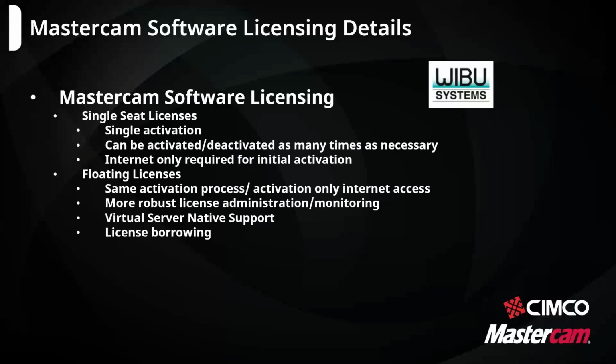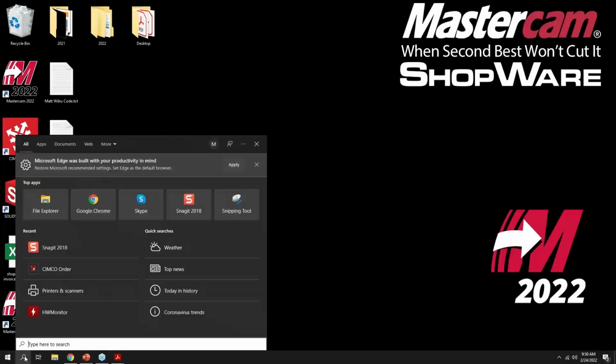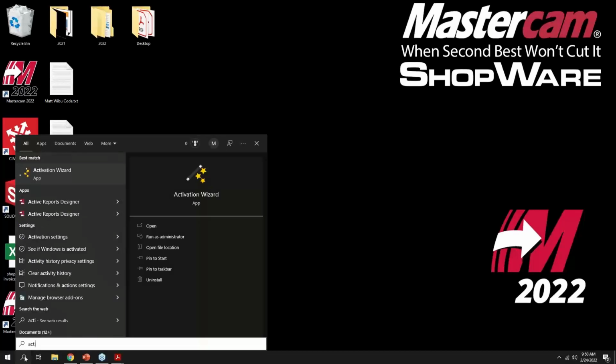You technically don't need internet ever, as there's an offline option, but the offline option adds a lot of delay to the process, because when you do the offline option, it creates what we call a license requisition file. And then we have to email that to Mastercam. They send us back an activation file that you manually load into the system. And it just takes a lot longer. I'm going to go through a quick example here of how that single seat licensing works. So I just search here. If I have Mastercam installed, I just search for Activation Wizard and it'll pop up.